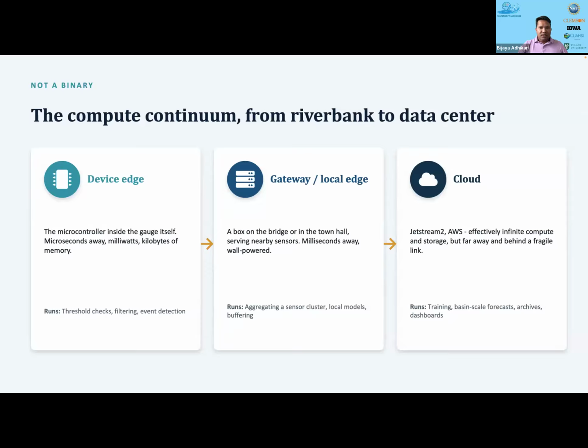Okay, there is one more question. Does the edge device transmit data to the gateway? Yes, usually yes, right? I mean, we can design things whatever way we want, but the most common framework is that the edge device runs on a battery and talks to a nearby gateway device through wireless communication. It could be radio transmission or, yeah, cell phone, using cell phone towers, right? There could be a series of gateways before the data is actually collected on the cloud, right? But at some point this gateway is going to be connected to a robust communication infrastructure.